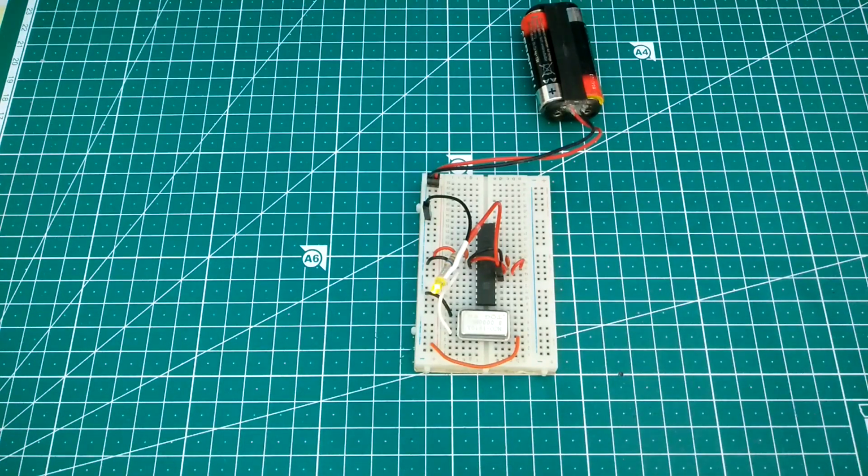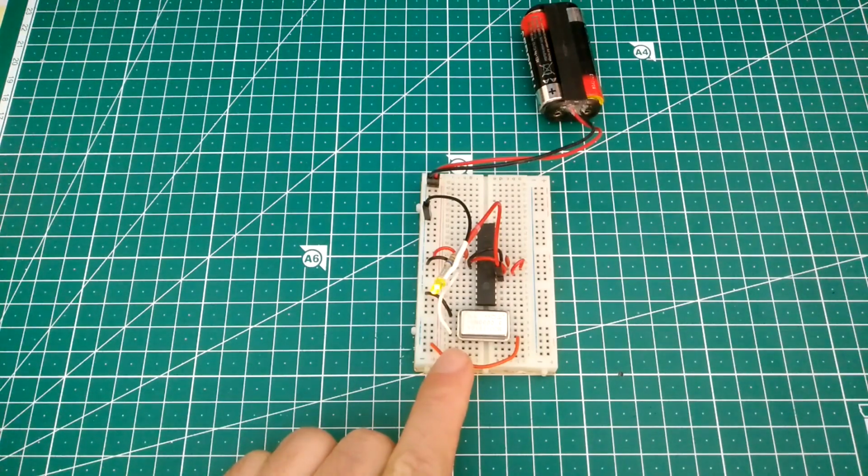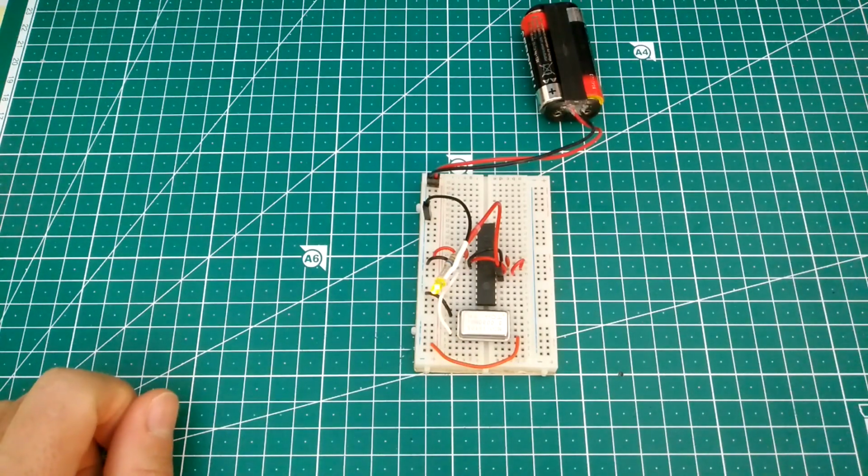There you go. So, why use an external clock signal for this one? Well, for this one it doesn't make that much sense. But there are, as I said before, microchips and even microcontrollers which do not take crystals. They only accept external clock signals. In some cases they have internal oscillators, but other things like waveform generators, they don't even have that. They require an external clock signal, and you have to provide it somehow. So, this little package, well, this big package, really, is a way of generating such a clock signal.